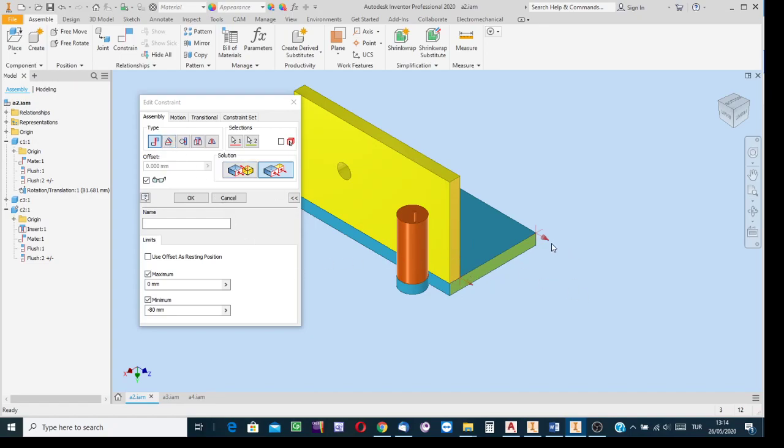Okay. Well, from the highlighting, I see that this constraint is for positioning the slender surface of the blue component and the slender surface of this yellow component with respect to each other. These are to be parallel to each other. Okay, so well, you see, the parallel positioning option has been selected.